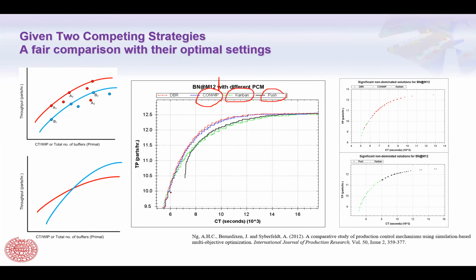In general, you can see that in this region I circled, the green part means that Kanban is in general superior in lowering the cycle time. But then there is a crossover point somewhere here, even though push systems in general are not recommended by industrial engineering professors, who always say that pull is better than push, and lean is better than make-to-order and so on.